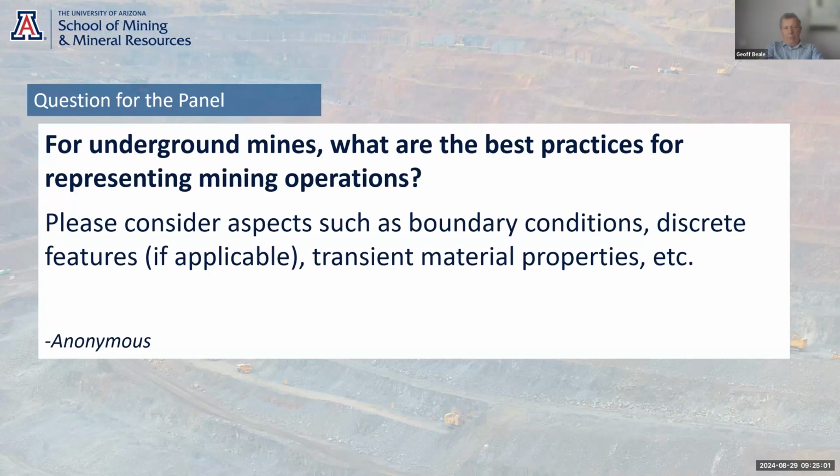Okay, I'm going to jump in on this one first. A big issue with many underground mines is ungrouted exploration drill holes. There are many, many underground mines that we're working on at the moment where most of the problem is due to water coming down from near surface in exploration drill holes. So that is a key consideration when it comes to trying to characterize it and to try and interpret the results of testing.